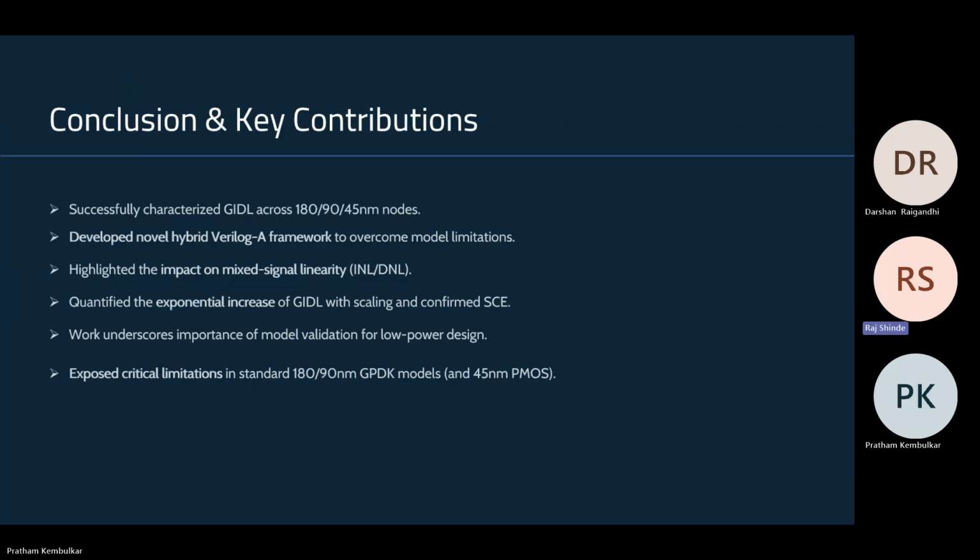To conclude, we successfully characterized GIDL across 180 nanometer, 90 nanometer, and 45 nanometer nodes and identified critical limitations in standard GPDK transistor models. We have also developed a novel hybrid Verilog-A framework that accurately captures GIDL physics, enabling realistic modeling of tunneling leakage.